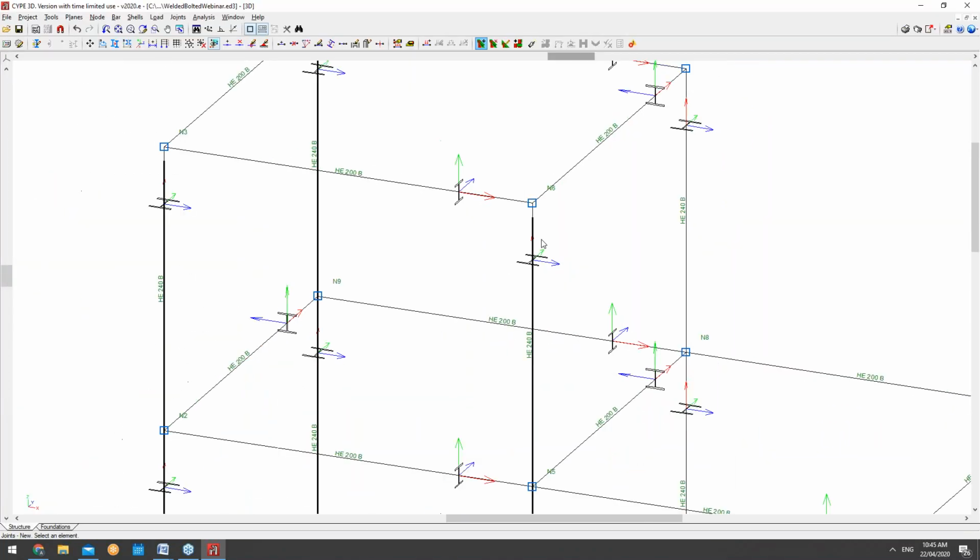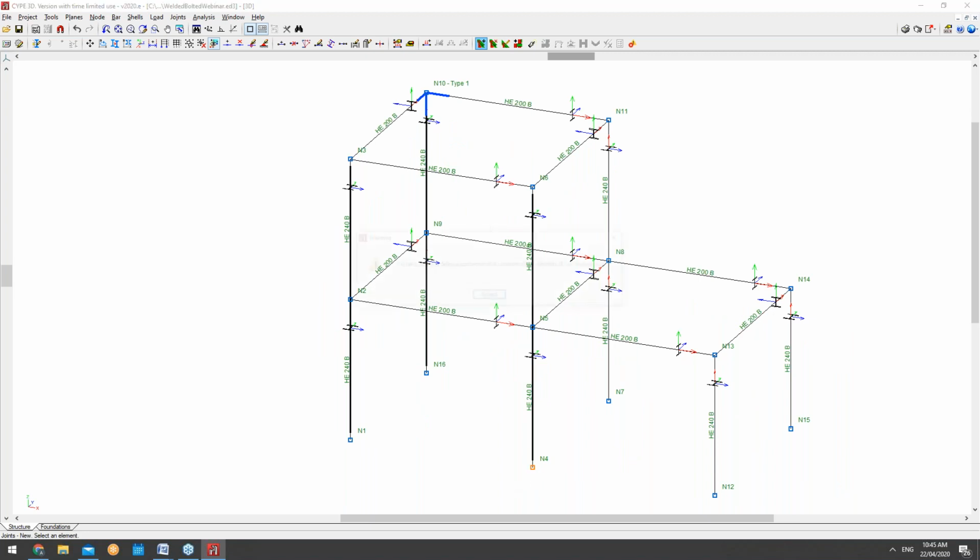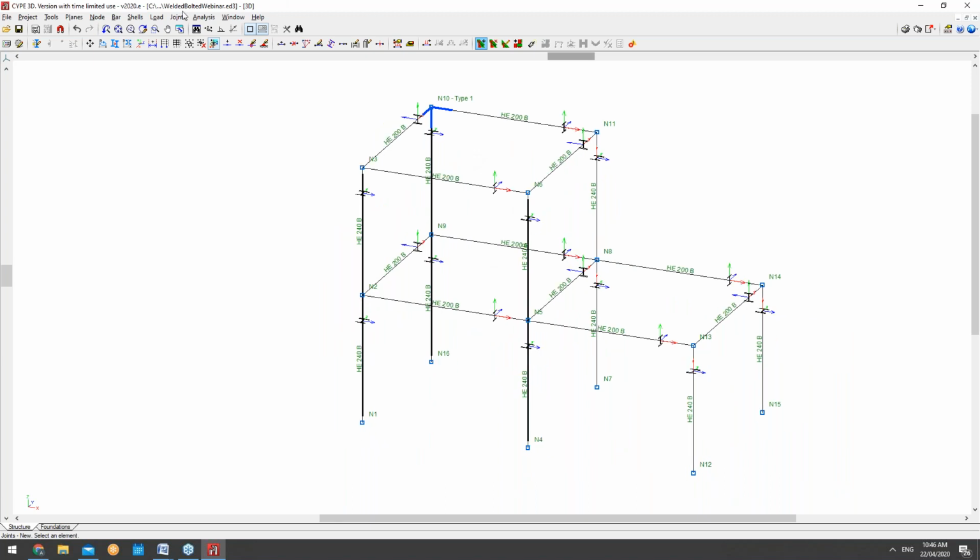Now let's save the change. Now what I can do as well is let's have a look at the capabilities on the whole. We can come over here to joints. Instead of generating each one, I can of course generate them all together. But before we do that, you can see here that I can assign and group certain welds as well. So what this basically means is, when we're dealing with material schedules as well, that same grouping is defined in those reports as well. So we can basically condense our views quite nicely.